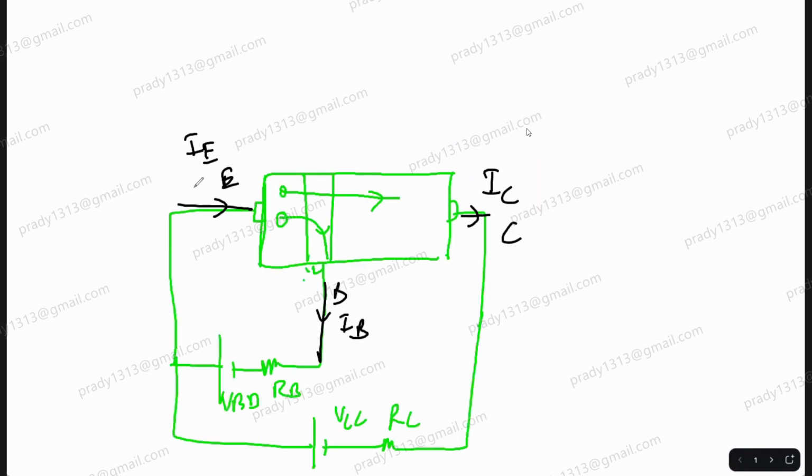Now this is how you represent a transistor. Now which is NPN, which is PNP. If you look at the NPN or PNP transistor, what did we see? Current is always flowing at the emitter base junction from where to where? P to N. Why? Because the emitter base junction is forward biased always.